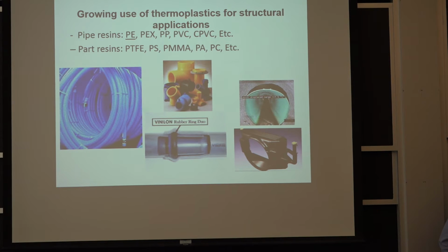And so the main issue with recycling, if it's a thermoset material, it means it was cross-linked. You can't fuse it again. It's just stuck in this state. You have to burn it. Now, that's the case of epoxy. Polyesters are that way, and they are used a lot for composites. So with composites, it's not only the issue that you have the glass reinforcement to deal with, but the resin itself can't really be recycled.